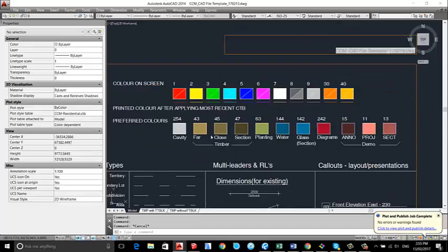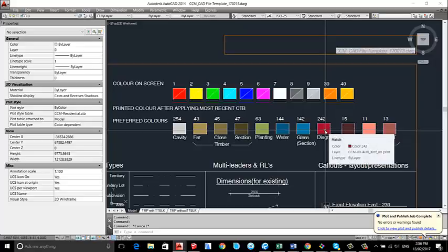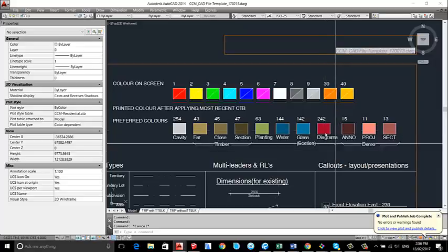Now then we have some other colors that are optional if we add color in the plan. One is for cavity or enclosed spaces, like for example the lift shaft, or the under space of a slab. Then we have 43, 45, 47, which can be for timber or for stone, just to add a bit of color. Then vegetation is normally 63, water 144, glass 142, and then one color for diagrams for real things that have to stand up, 242, but this is just a suggestion. And then colors for demolition.